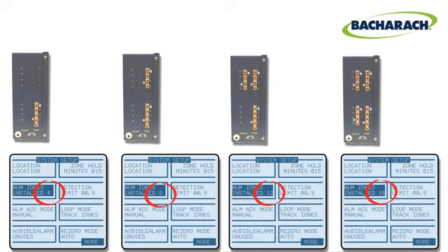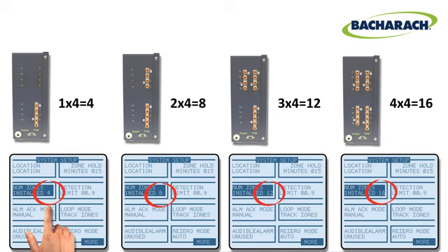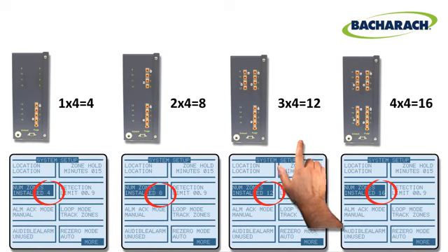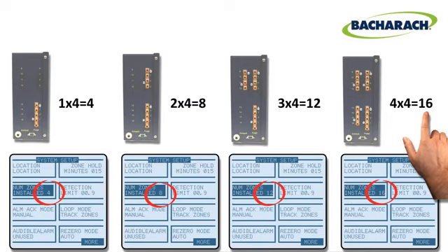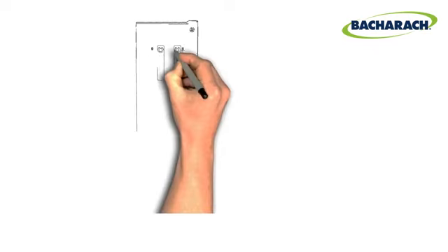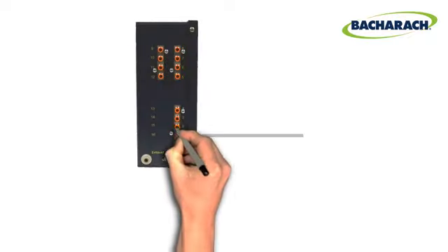To do this visually, inspect the side of the MZ chassis and multiply the number of manifolds by 4. This number should match the number in the Num Zones Installed setting. If not, change it.